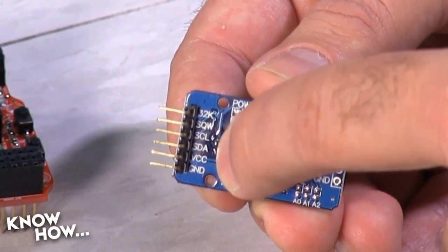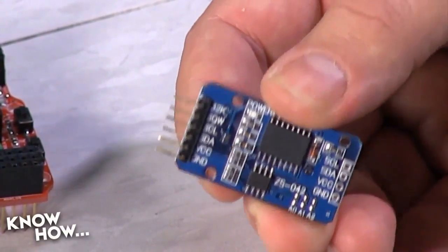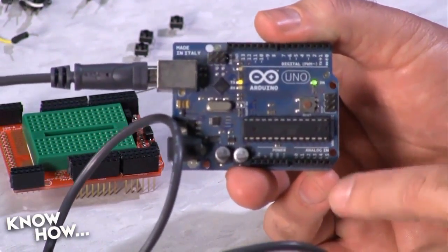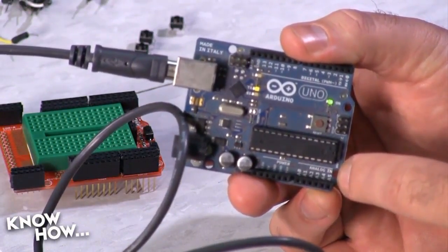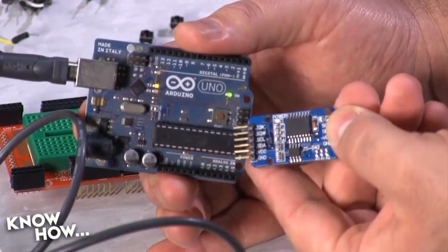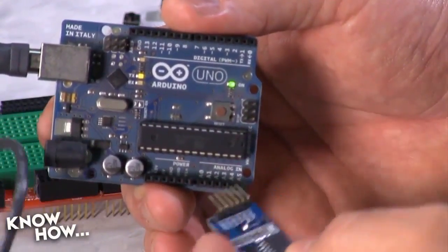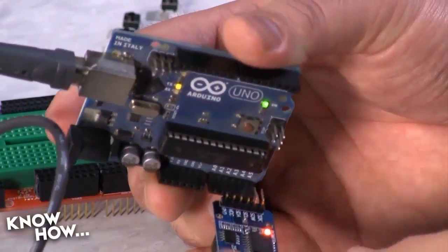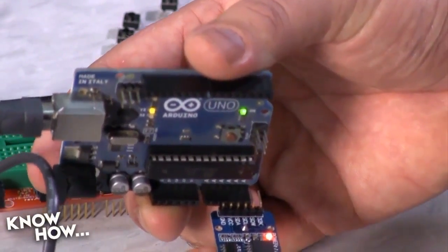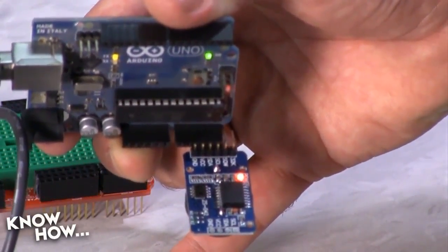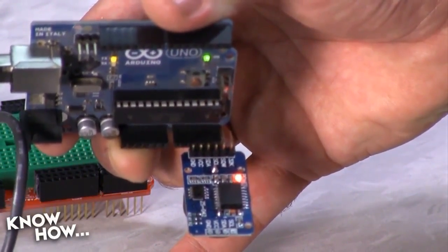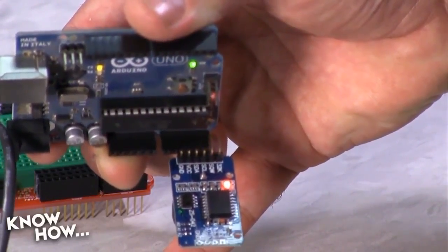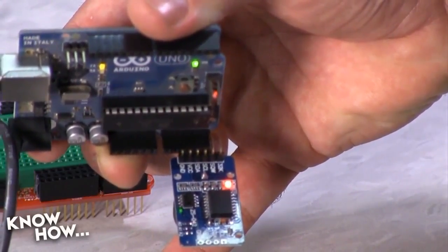We're going to be using the I2C bus out of this. On the Arduino Uno, I2C is on pins A5 and A4. If you look at the pins on the real-time clock there, I can actually put the real-time clock into the Arduino directly like that. We're not using the 32K, and we're not using the square wave, but if you put them in like that, that puts the serial clock and serial data in the correct pins, and then I just need to configure the Arduino to give a positive voltage on the VCC and a negative voltage.